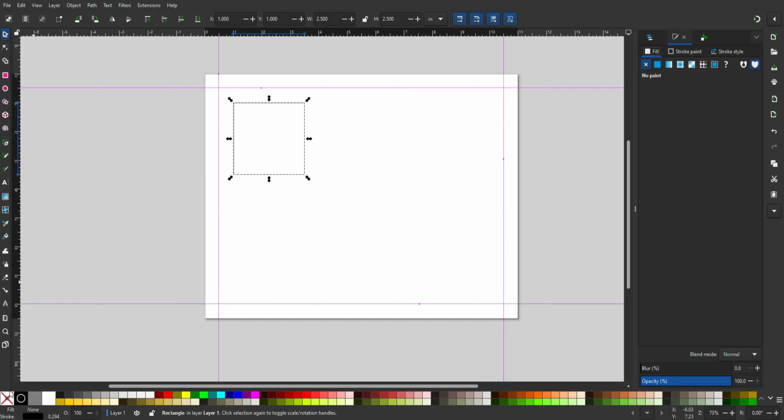And with your laser cutting, the laser cutter has 2 settings. One is the cut setting and one is the etch setting. The cut setting always needs to be a vector. The cut setting is going to be a higher power on the laser so that it cuts all the way through the material. The etch setting can be a vector, but it can also be a raster image.